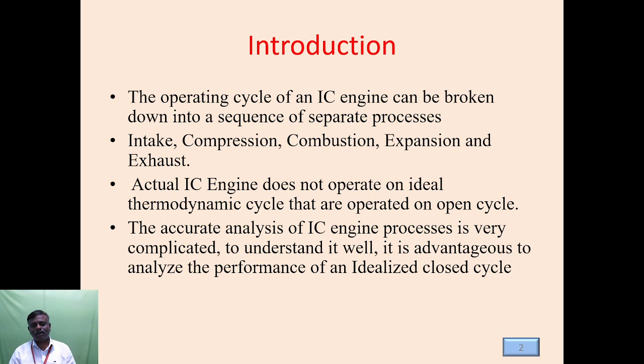Introduction. The operating cycle of an IC engine can be broken down into a sequence of separate processes: intake, compression, combustion, expansion, and exhaust. An actual IC engine does not operate on an ideal thermodynamic cycle; it operates on an open cycle. The accurate analysis of the IC engine process is very complicated. To understand it well, it is advantageous to analyze the performance of an idealized closed cycle.